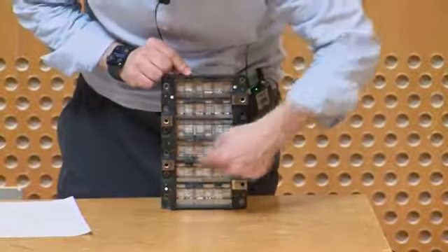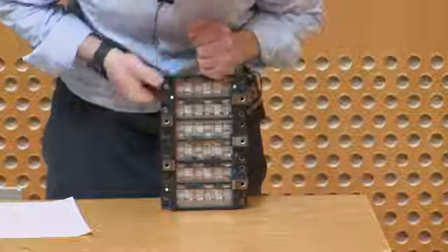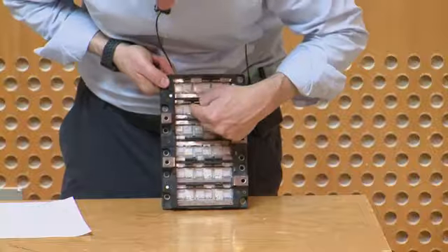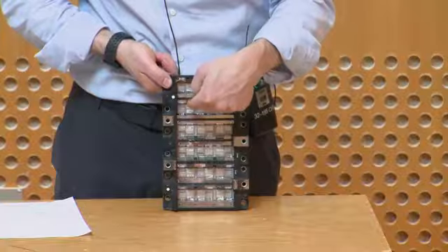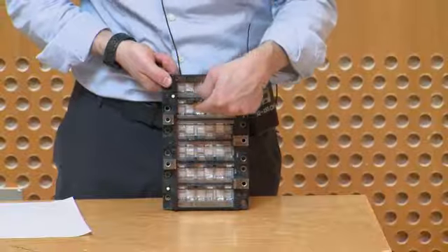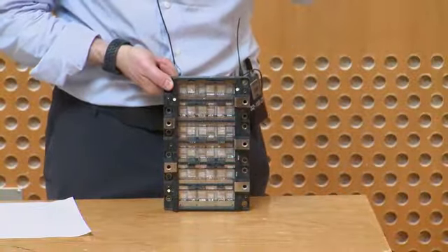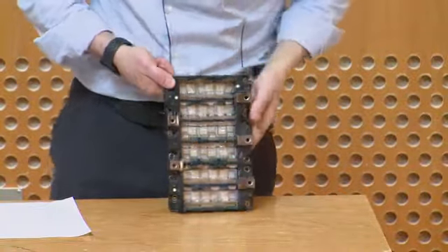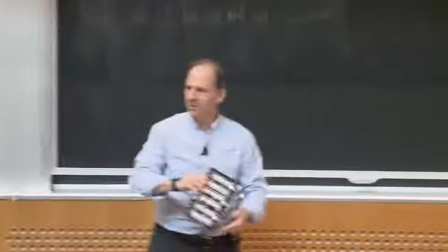Each of these, what you'll see is a pile of devices in parallel in order to provide the required power. And when you look closely at this, you're going to see that there are essentially 3 terminal devices that go back to gate drivers. Those are the IGBTs in this older model. Today they use silicon carbide FETs. And in anti-parallel with them, because the IGBT can't carry reverse current, they have actual diodes. So in their design, the actual diode is separate from the actual switch. And so I'll pass this around, you can look at it.